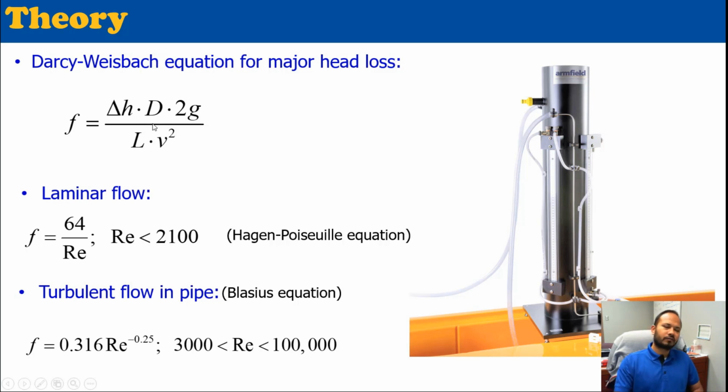Now, this is the friction factor from experiment. We need to compare the result that we determine with our empirical results. If you remember your Hagen-Poiseuille equation for laminar flow, where your Reynolds number should be below 2000, you can directly find the friction factor using this formula.